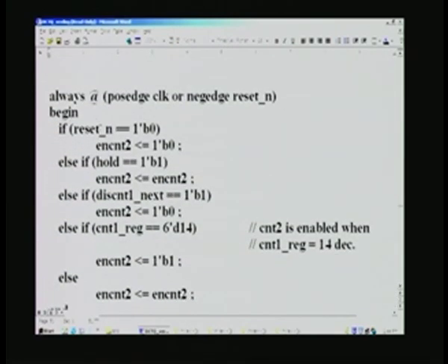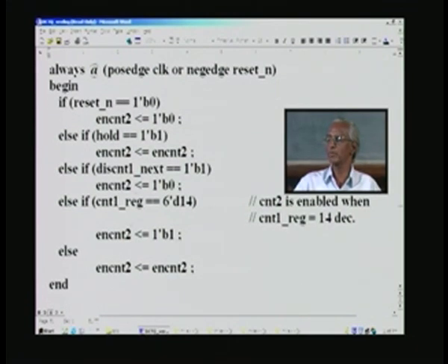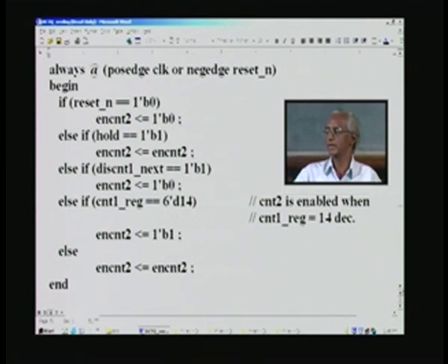So, once again you see in the design one signal in only one always block. This is a good practice, I hope you will follow the same, and if you take hundreds of signals in one always block, you will get drowned. So, it is a good practice to have just one signal, and very rarely violating that if the need arises, which we may see later on. And similarly for reset, hold, etc., same, and it has to be cleared if counter 1 is to be disabled.